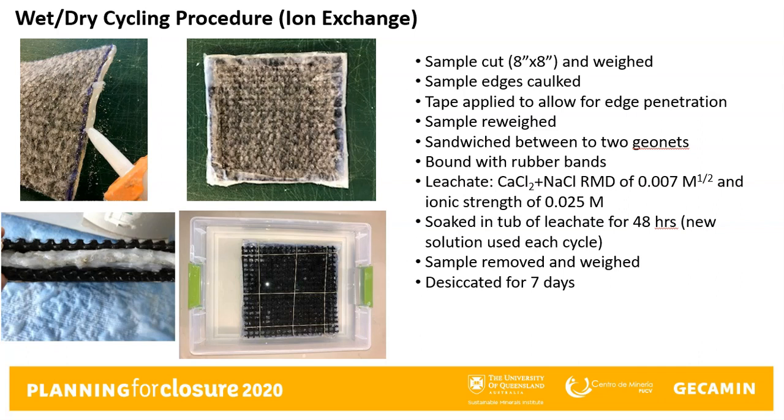The samples were allowed to hydrate for 48 hours in mild calcium chloride, sodium chloride leachate solutions, which had an RMD of 0.007, so very low, and an ionic strength of 0.025. The samples were hydrated for 2 days and then taken from the bath and allowed to desiccate for 7 days.